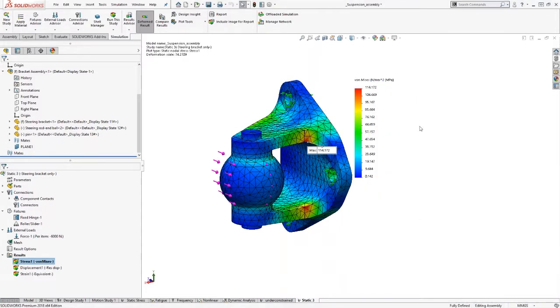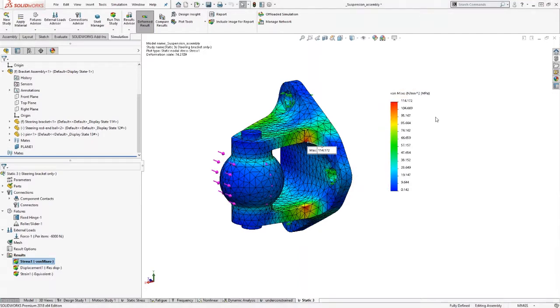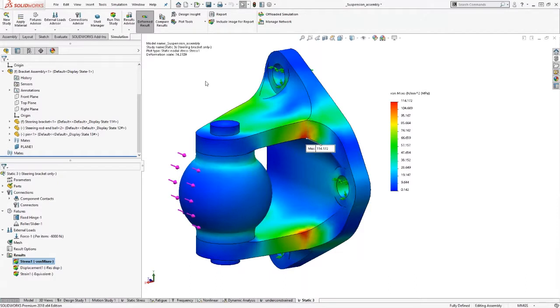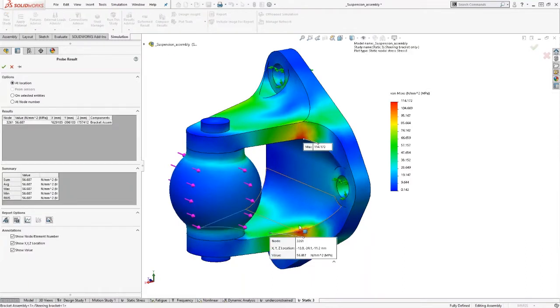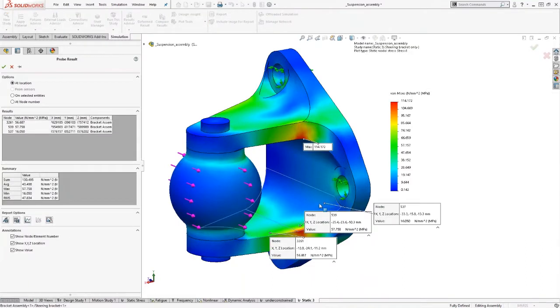That shows me that finite element mesh broken down over the model, and we have full control over that mesh. We can increase the density of it, refine it in certain areas if we want to. There's a lot of control there that we can use. And then there's a lot of tools to interpret the results in more detail that, again, you wouldn't have in a simulation express. So we can probe and basically choose points anywhere we're interested in and get exact measurements there.